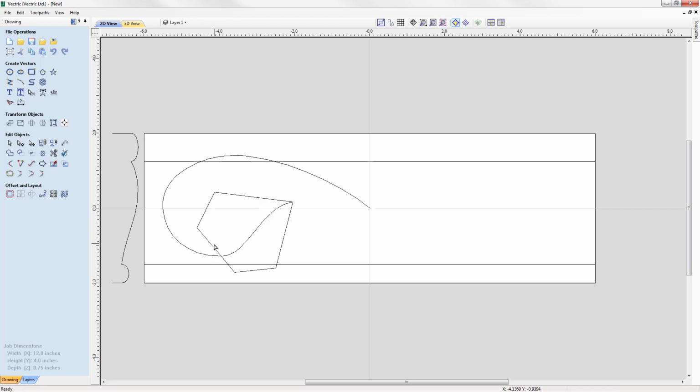Right then, so let's go ahead and look at editing just the leaf. So I'm just selecting the leaf here, and what I want to do is I want to look at smoothing these points. So with those selected, I'm going to press S on the keyboard to smooth those, and then we're going to box select these two nodes here and press S to smooth those. So again, like we did with the stalk, we're going to look at altering the shape by pulling on the handles, moving the control points, pulling on the spans until we're happy with the shape that we've got.